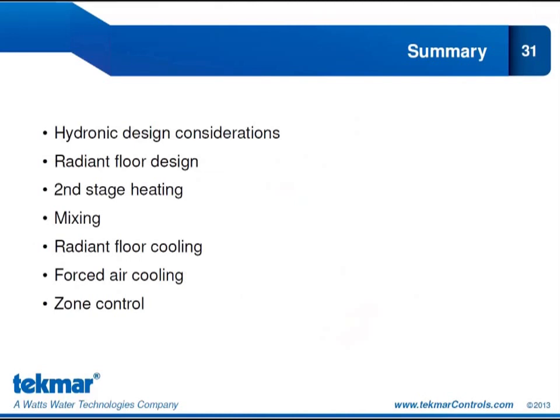And mixing is even more important if our design includes radiant floor cooling. We need to supplement our cooling with forced air cooling, and radiant floor cooling, which is subject to dew point reset, will require a very different water temperature than a fan coil would for the forced air cooling.